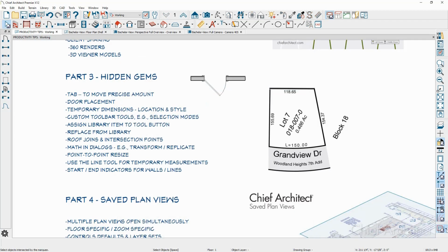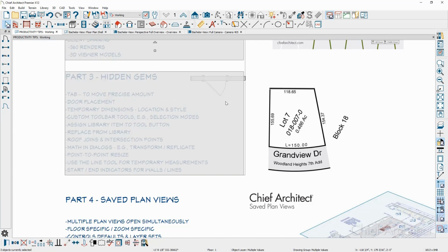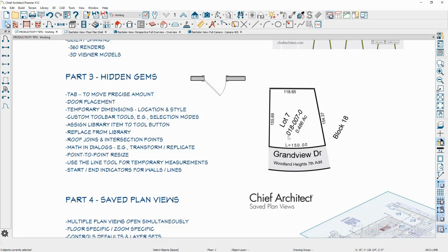Now when I change my mode, let's drop that down. Notice that it's currently intersected. That's why it selected both text objects as well as the door. If I change that to be contained in, and I click and drag a marquee, it has to be contained in. It's only going to select those. Versus you switch that back to intersected and you draw a marquee that kind of looks like this. Anything it touches, it will select. So depending on what you're doing, you can toggle that around and adjust it. I use it a lot in my process, and if you find it handy, you can also add that on there.